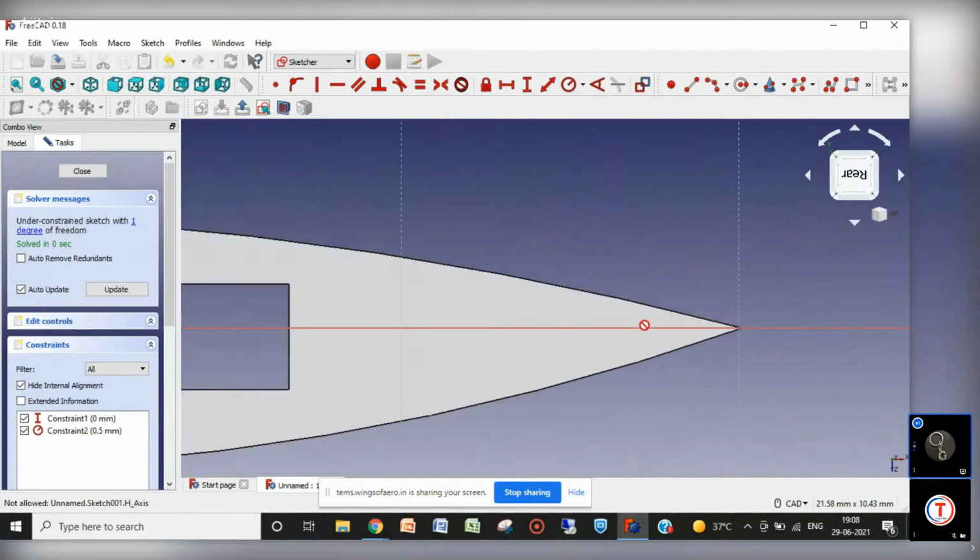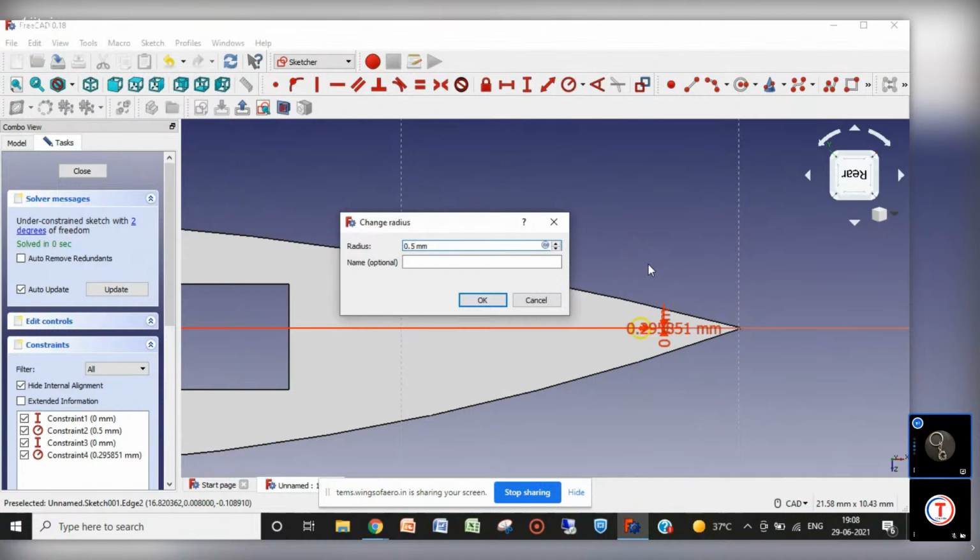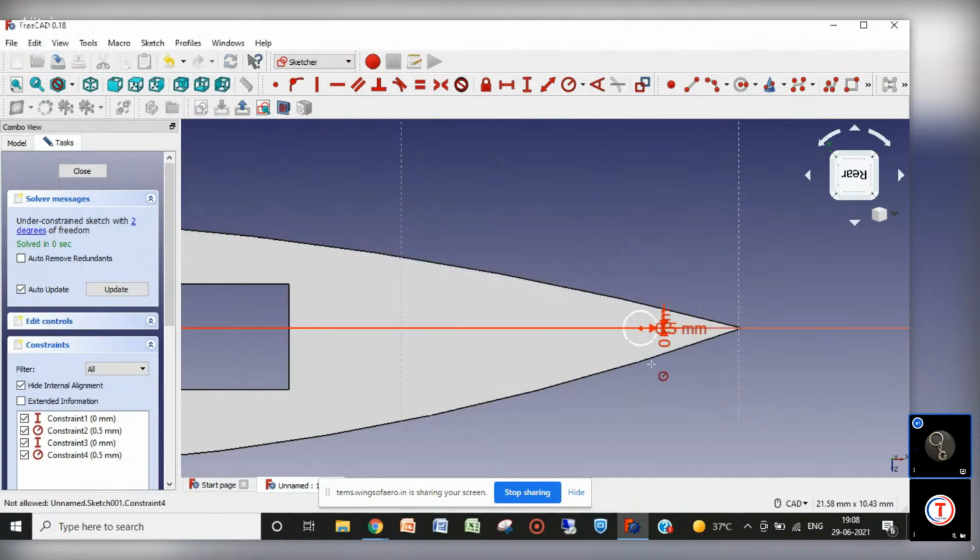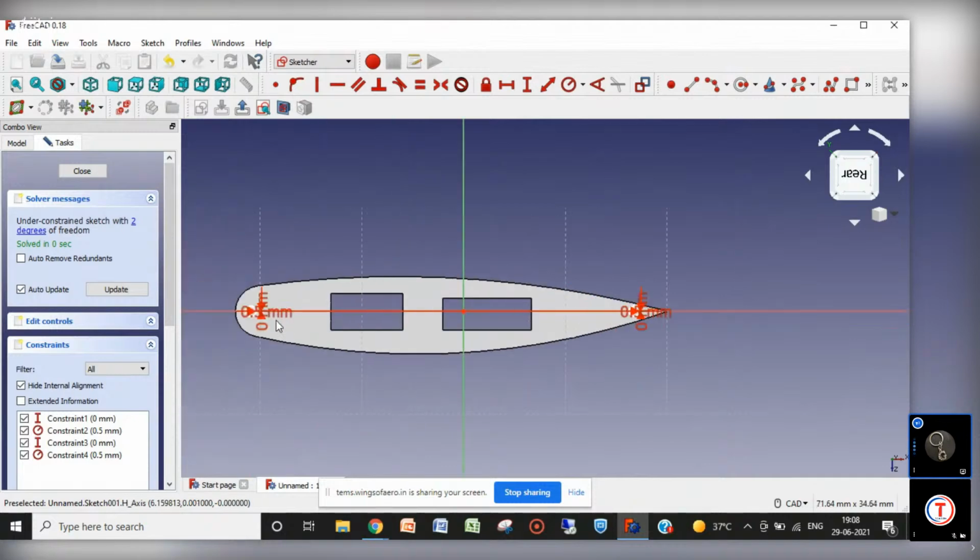Okay, and another one at the back. These two I am making circular spars. At this point vertical distance 0 and the radius of this circle let it be 0.5 only. Enter. If we can place it accordingly. Now a few of them would be rectangular, so I am making those also. One here and one here. We are not using many ribs.